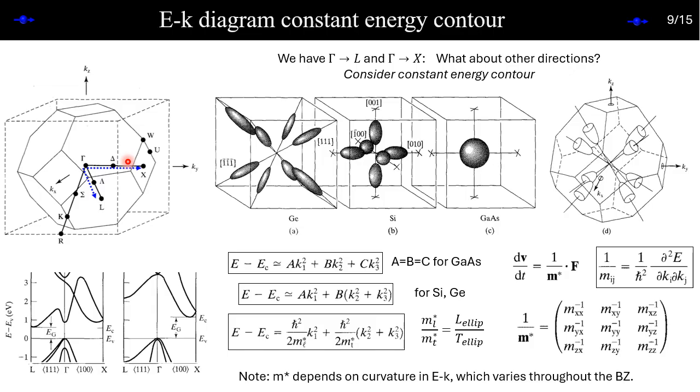Kx, ky, kz. But here, for silicon, we don't take it because the high symmetry directions are along the 111 point, where you have the conduction band minima. This is important. We are interested near the conduction band minima. So let's define the k-axis along these. If you define the k-axis along one of these diagonal directions, the other 2 are easy, just 2 perpendicular to these. Is it okay? Or do I need to repeat?